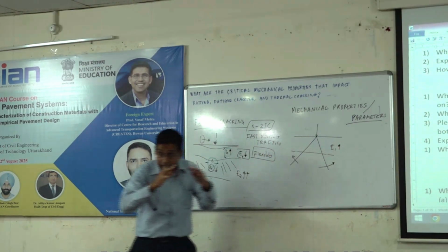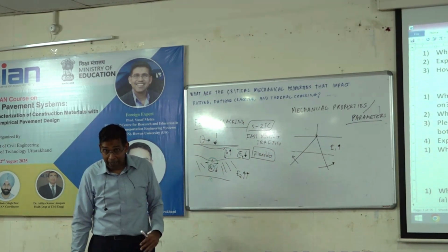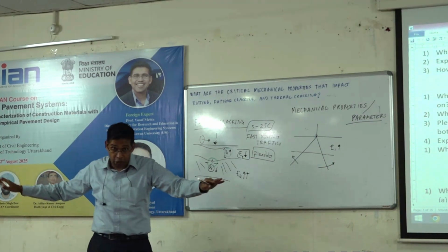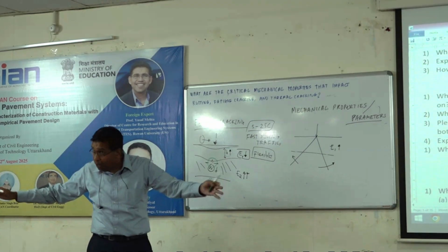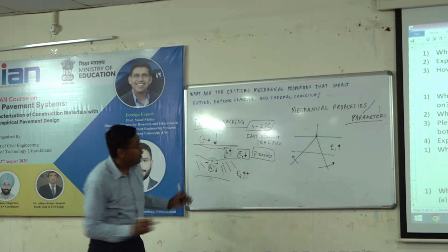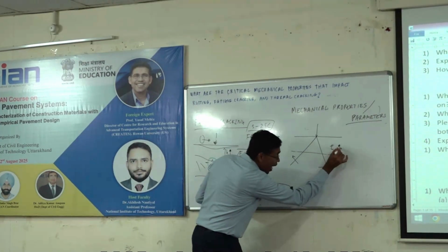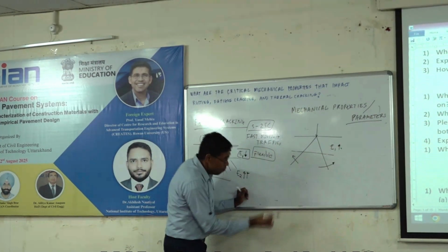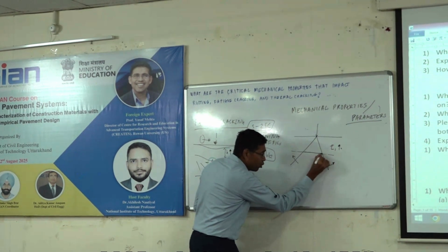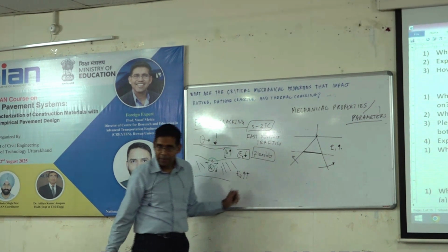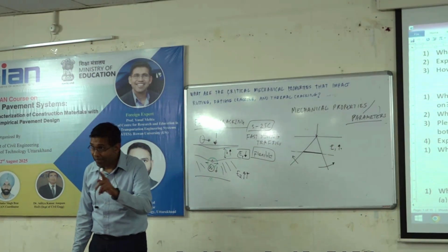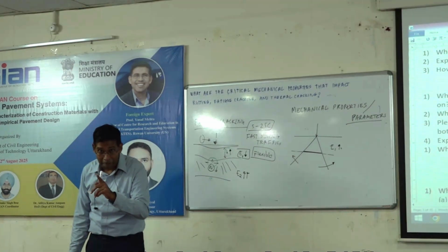That means that thing becomes more efficient, right? Remember, I gave you the example of steel. If I put a steel slab, the cone of distribution is going to be completely flat. Very efficient, but very expensive. I want you to pay attention here. If I make this very hard, the cone of distribution is going to be very wide. What are the stresses going to be here? Negligible. Very low. You are absolutely correct. Is everybody with me so far?